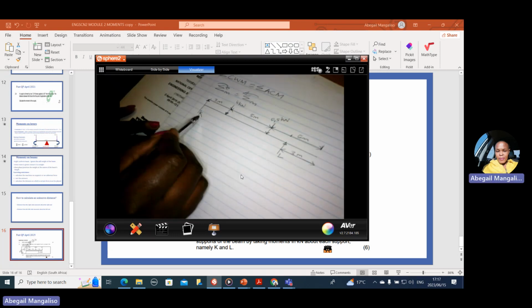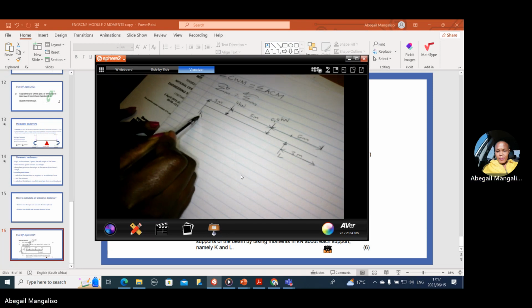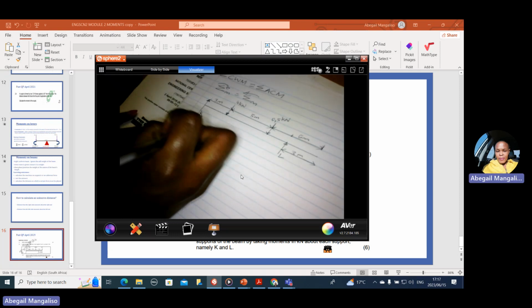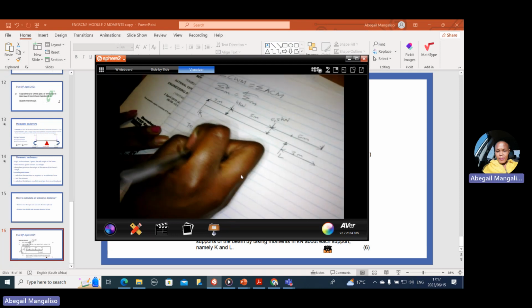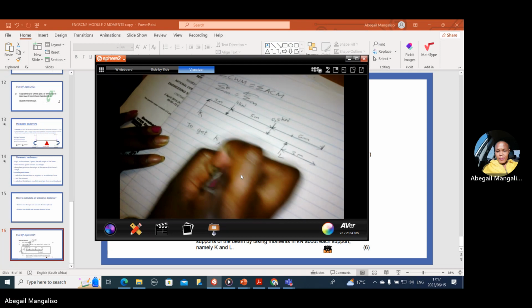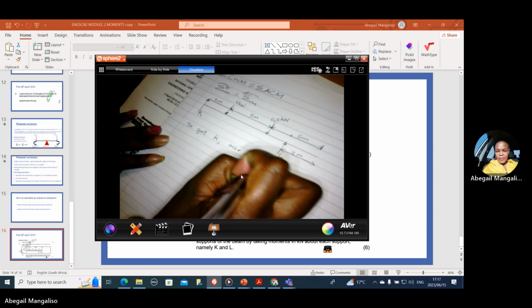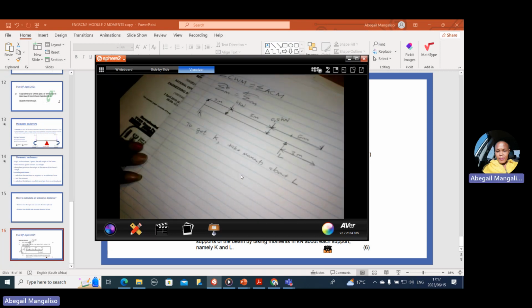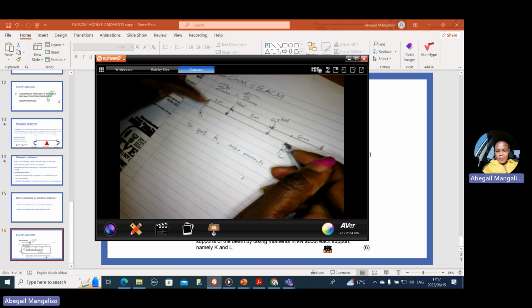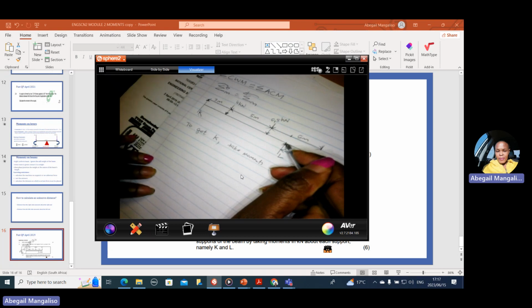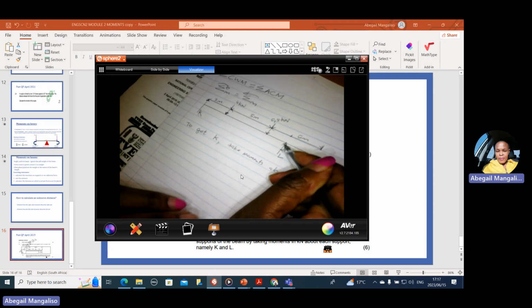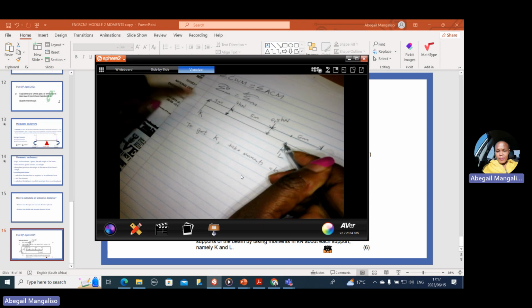Now, in order to get the value of K, you need to fix L. So to get K, you take moments about L. If this one is fixed, this one is free to rotate the structure. You take moments about the other support. You cannot fix L and still get L. When L is fixed, K is free, you're going to get K.